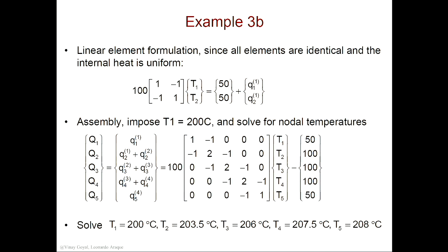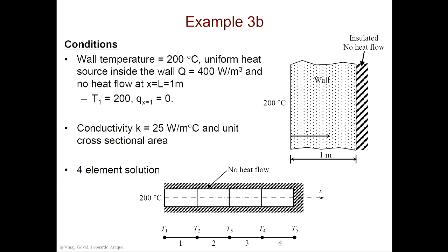Okay. For heat generation, this became 50 and 50. Okay, and you can check that makes sense. I won't do it now, but you can check it at home. Well, actually, you can check it here. When you assemble the whole thing, you get 50, 100, 100, and 150. Okay. Add this together. What is that? 400. Well, I just told you that I applied 400 internal heat generation. But when I did the integral of Q against the shape functions Ni and Nj for a linear element, it told me how to distribute that load.